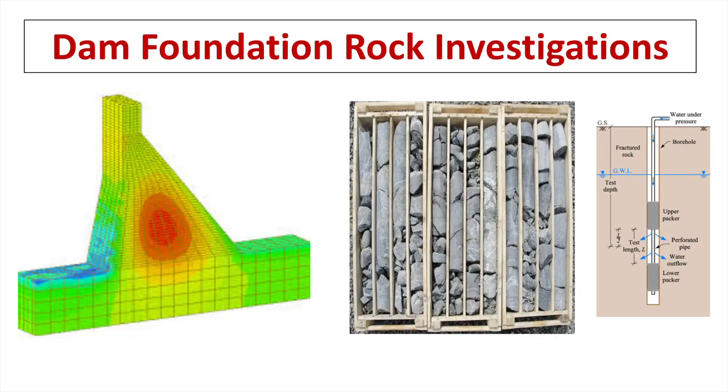In this video, we will learn about dam foundation rock investigations. Knowing the properties of foundation rock is extremely important to study the behavior of the dam along with the foundation. A weak foundation may cause the dam to settle, and a permeable foundation causes seepage issues. Investigations also help us in locating weak zones in the foundation, so we can adopt or design solutions for the respective foundation problems.